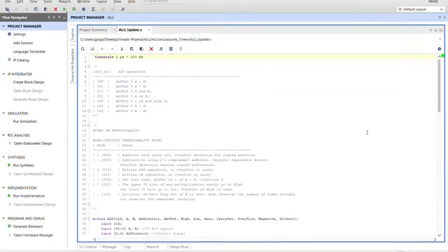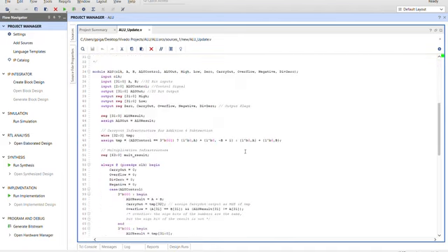So this is our ALU. It's responsible for all arithmetic and logical operations of our processor. As you can see, it has add, subtract, and, or, if less than, multiply, and divide functionality. Essentially, it takes in two 32-bit inputs, does whatever you need it to do, and then raises any flags corresponding to those operations if you need it.